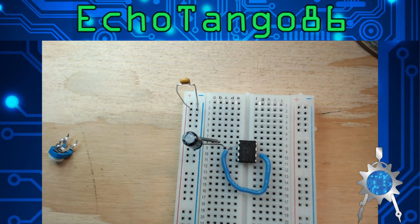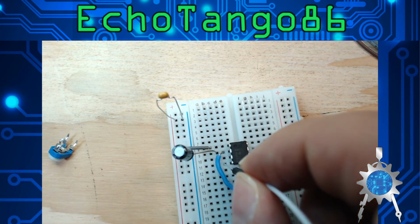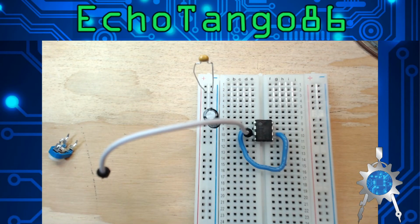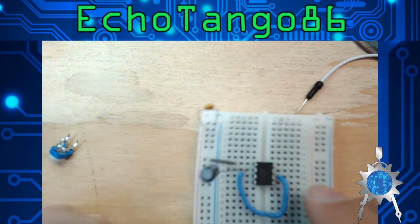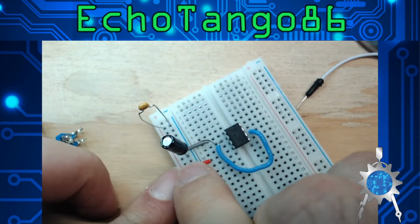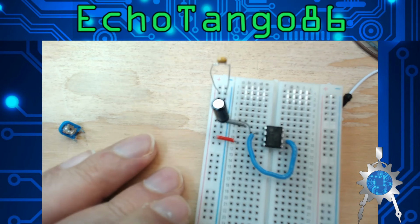Pin 3 is our output. Now I would recommend having a wire for pin 3 to come out for your output. So now you know that that's your output. That's going to go to whatever, and it makes it a little easier to do. Now pin 4. Pin 4 goes to a positive. So I like to use red or yellow or orange to signify my power. Those colors tend to stand out a little better. So what we'll do is we'll pull that out of pin 3 for now to clean it up, and put this in here like so. There we go. So you have red going to pin 4, which is nice.